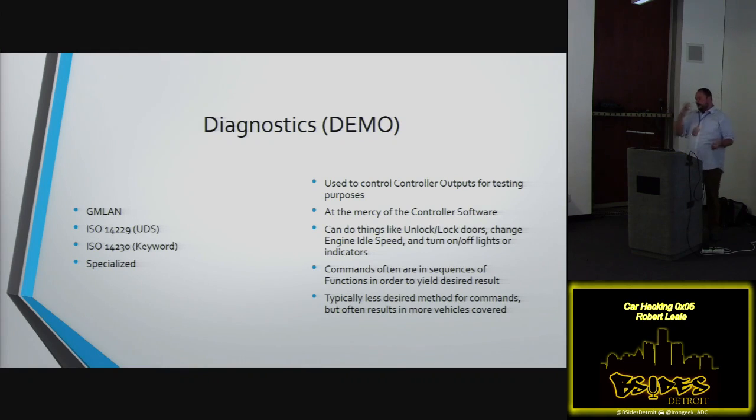Essentially, if you wanted to, part of diagnostics is not just I/O control, but reading memory, right? So if you wanted to dump the firmware, something fun to do, you just ask it, hey, what's in memory address 0x800000? Could you give that to me? Oh, here you go. Give me 5 bytes of it. And then give me the next 5, the next 5, the next 5, et cetera. And you can just walk memory. You can see what's going on in RAM, what's going on in ROM. Not all vehicles allow you to do that, thank goodness. But a lot of them do. And it's usually the higher end controllers, the ones that you're really more interested in anyways.